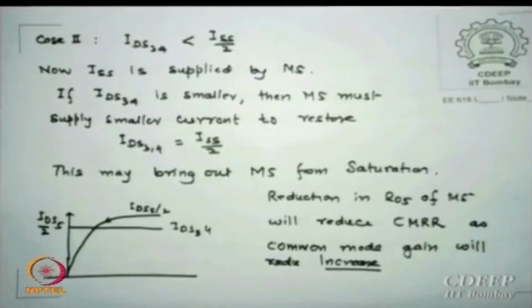Many people believe this never happens, but it is not so, it does happen, and you need to put a circuit called common mode feedback, which retains the common mode. If something increases it will reduce, if something goes down it will pull it up, so that CMRR always remains constant, and so do the gain and the output resistance, remaining as high as they can be.